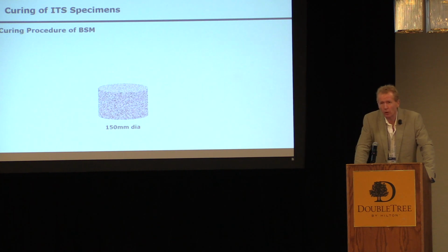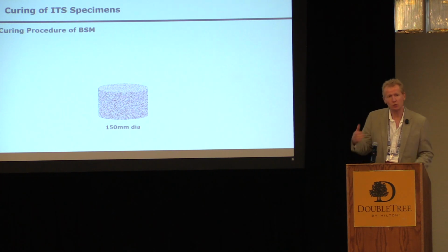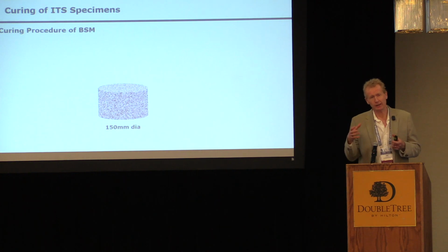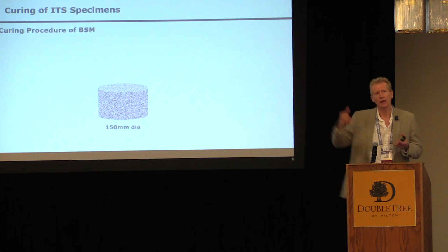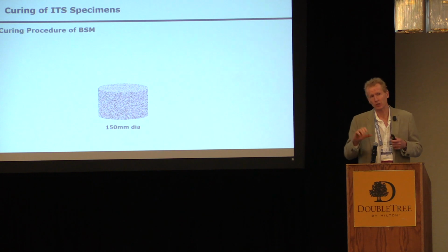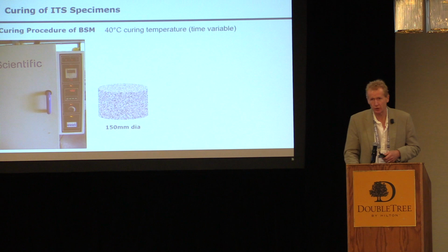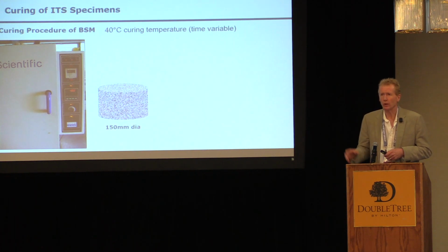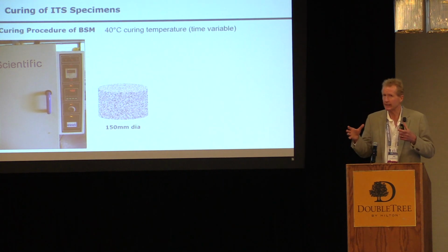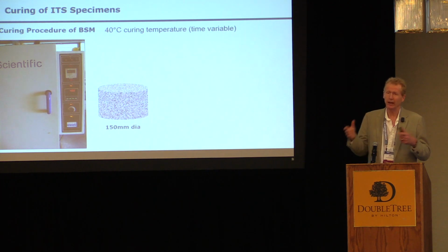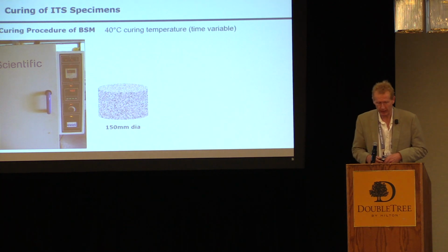In terms of curing the material, the other thing one needs to understand is that this bitumen stabilized material, whether emulsion or foam bitumen as binder, needs time to gather strength as moisture is driven out after compaction in the road. And you can see a stiffness gain and strength gain for up to a year after construction. So we need to simulate this in the laboratory. If we differentiate slightly now between ITS testing, and later on I'll mention the triaxial tests.